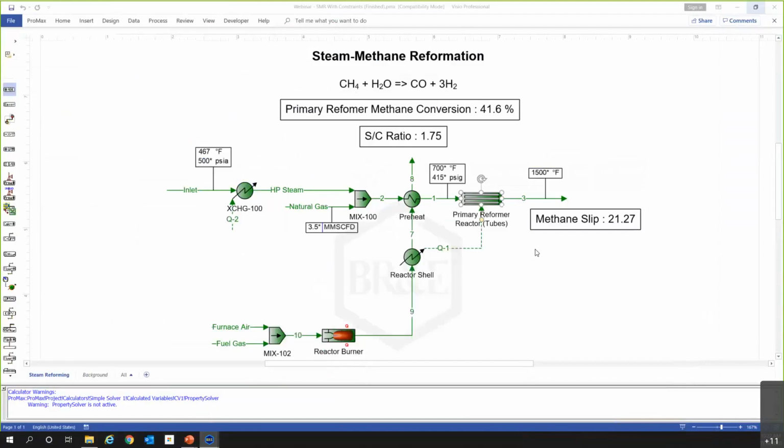With that, we now have a reactor that's going to operate within those bounds. So it's going to be able to match our plant data a little bit more accurately and match that catalyst activity. If you have more plant data points, you can go ahead and add them as you please, and it will just make this reactor run a little bit more accurately. So once we've inputted those constraints, we can now look at the scenario tool. That's going to be the second step in solving this case study issue that we're having.